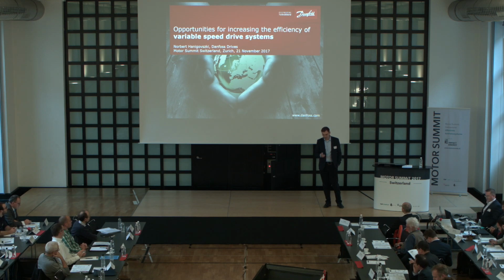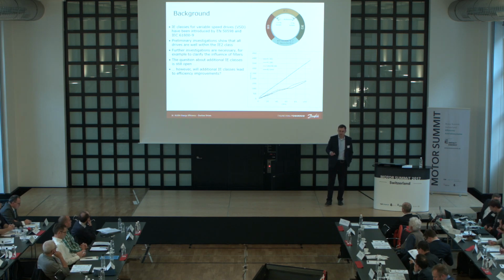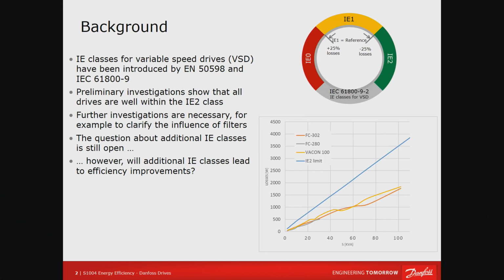The topic is about opportunities for energy savings in drives. For the last 3 years, we have had energy efficiency classes for drives, first introduced by the European standard EN 50598, later by IEC 61800-9. There are 3 classes, IE0 to IE2, and preliminary investigations show that all drives are class IE2.